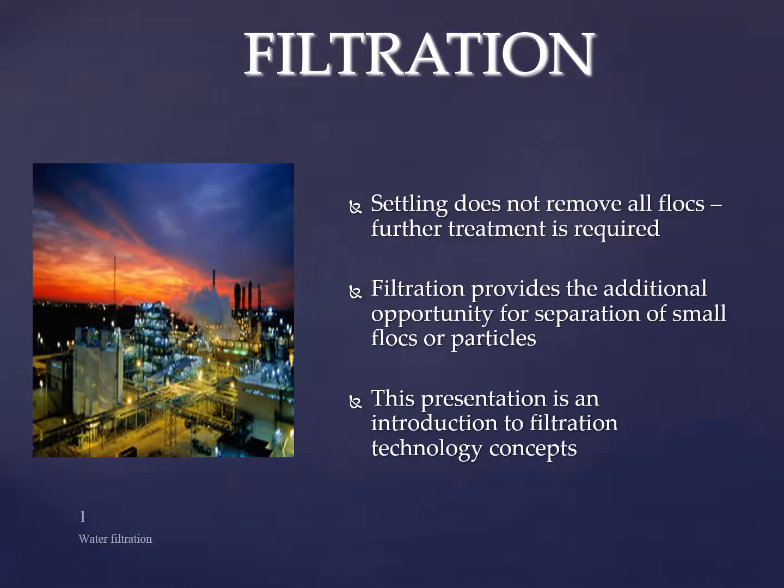Section 13 is about filtration. Based on drinking water standards in the US and most other countries, surface water should be filtered and disinfected. Settling does not remove all floc, so you cannot remove all of the bacteria and microbes, Giardia for example, Legionella, and other bacteria. So you need to design filters.